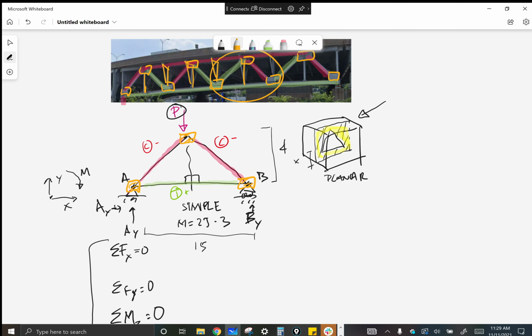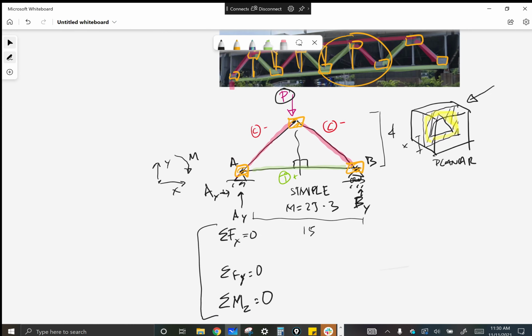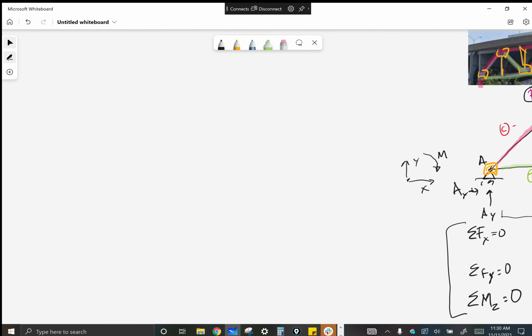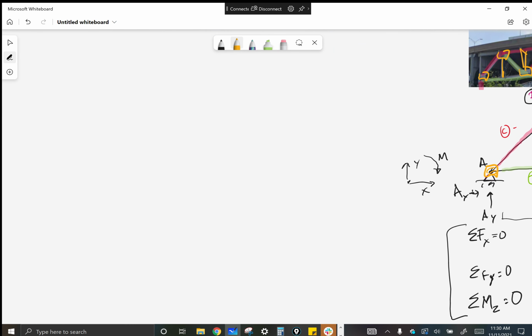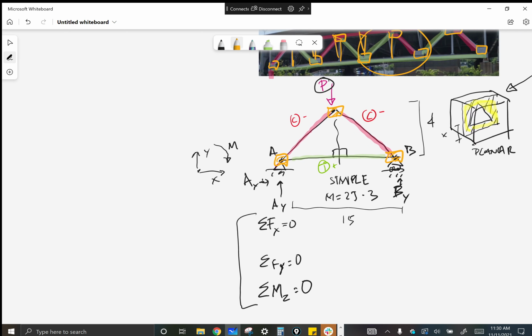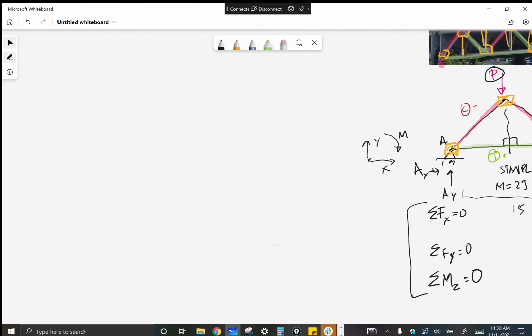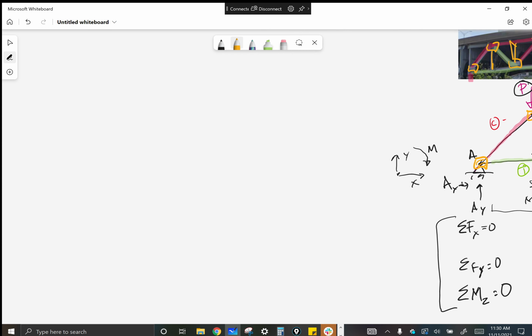But then in the theory, there's another thing that I've talked about, but maybe you guys haven't gotten, so I'm going to spend time on that right now. And I promise this will end at some point. But to me, this is all interesting, and it's what we've done in the class. Why do we call these joints hinged? Anybody remember? Yeah, they don't resist moment. Right. Perfect. What named joint that we have talked about does resist moment? Do you remember? Gusset.